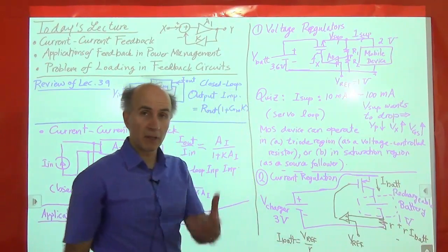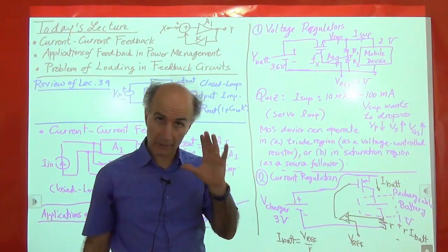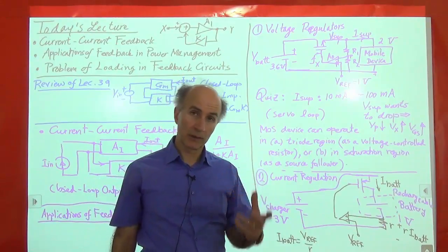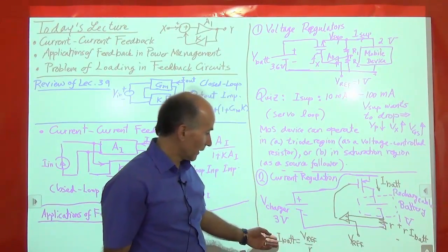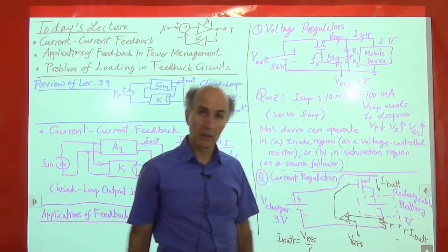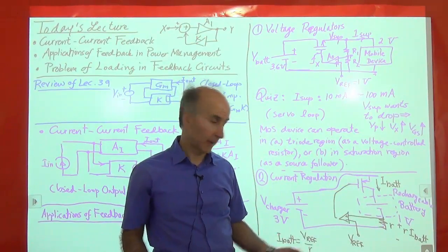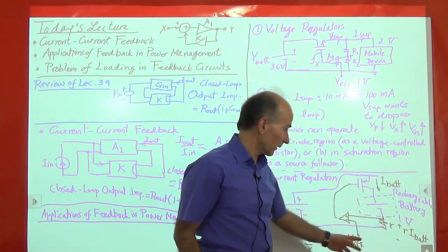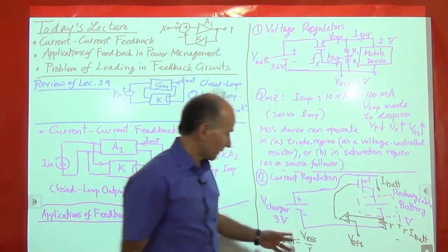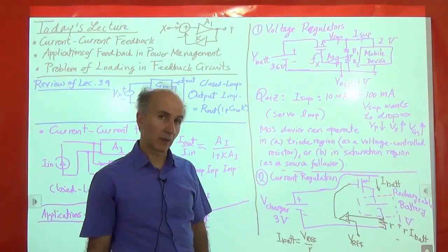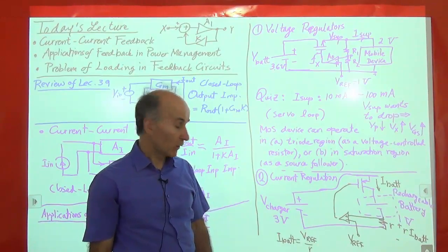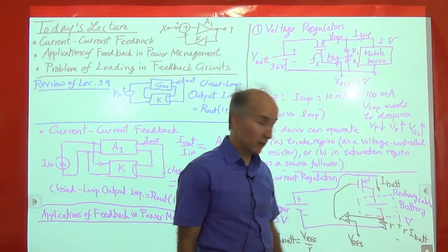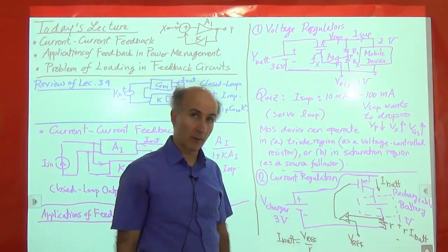So now, given that Vref is provided by us, and it's a good voltage, it's a constant, well-defined voltage, and hopefully R is also a good, constant, well-defined resistance, this ratio tells us how much current we are applying to the rechargeable battery to charge it up, right? And that's what this loop does. This servo loop wants to make sure that this voltage is a good copy of this, which means this current satisfies this equation, and we know how much current we are applying to the battery. This is another example of power management. We're managing how this battery should be charged up from the discharged state.